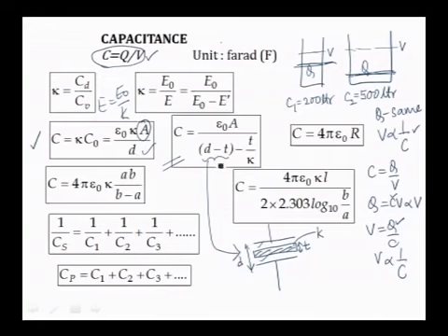And now this is important because if you put a metal for one portion of the capacitor, the dielectric constant of a metal is infinite, and therefore this part becomes 0. So it is as though this much of the capacitor is absent because I have put a metal here. This can be imagined as one small capacitor and another capacitor, and therefore this part can be squeezed to 0.